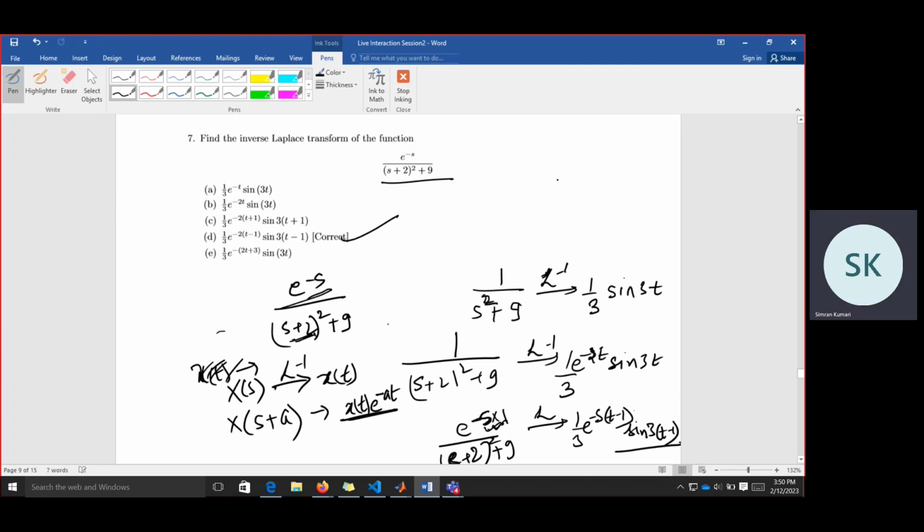Like we had in the Laplace transform for x(t), if we are multiplying with this exponential, then there is a shift in frequency. So it is saying the same thing, just reversed. And then if this one is X(s) e to the power minus s t naught, this is x of t minus t naught.